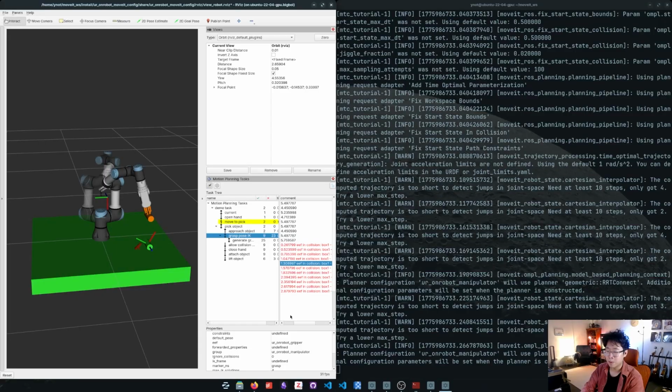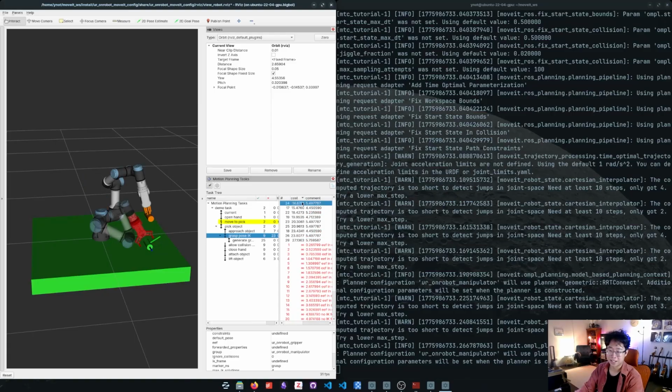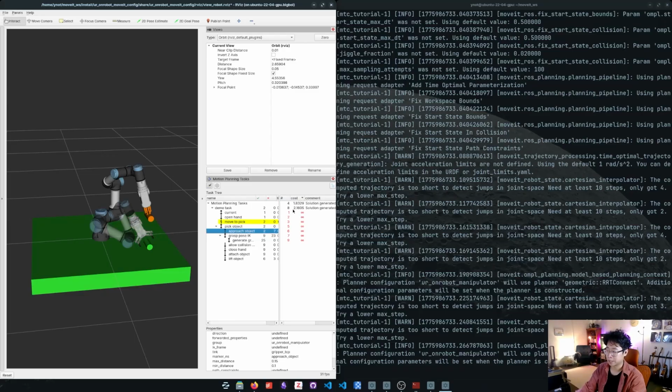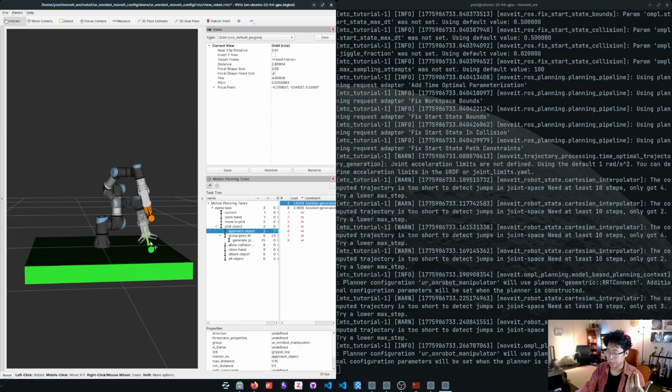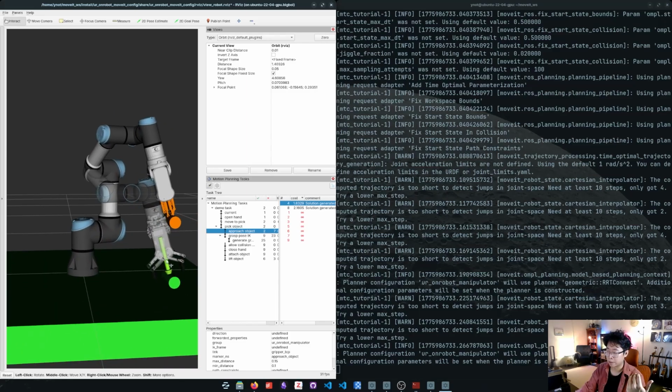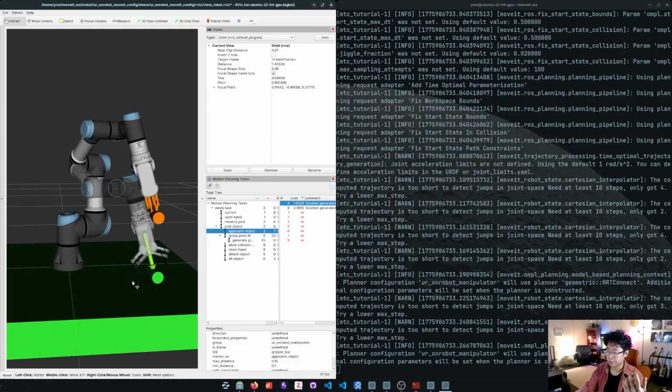Yeah. So the robot basically goes through all possible configurations and solves for IK to attempt picking, and this solution will actually propagate into the past. Right? So depending on the grasp pose, it will determine how to approach the object. From the grasp pose solution, it will generate this approach object, which is this distance away from the object that we defined.